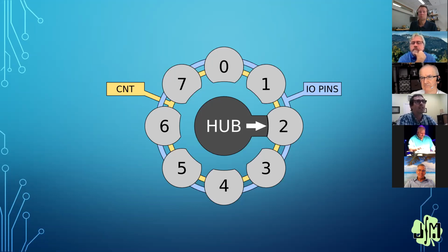Okay. So this is how it's possible for every cog to read and write a 32-bit value, like streaming in and out of the hub memory continuously. Oh, nice. Okay. It's not having to wait for one thing to come around. It actually waits for the address of interest to come around, and then it starts streaming data out, or it starts picking data up.